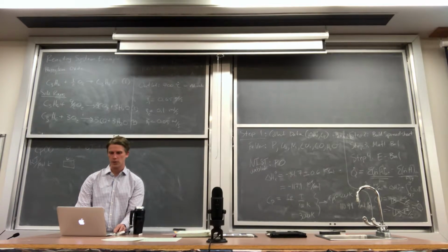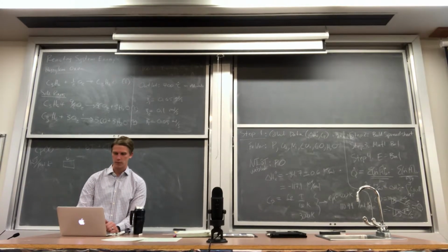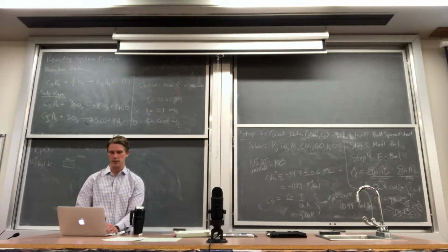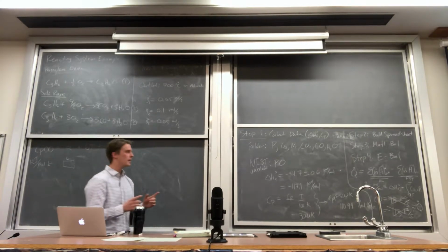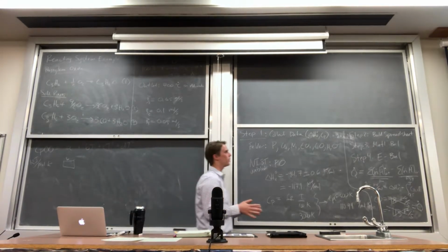So I'm just going to go to goal-seek, because this is a relatively simple system. I want to set my Q equal to 0, and I will change the outlet temperature. And let's see if it works for me. Voila. Our Q is times 10 to the minus 7, and that means our outlet temperature comes to be about 1300 degrees Celsius. So what this is saying is that this process is a fairly exothermic process.